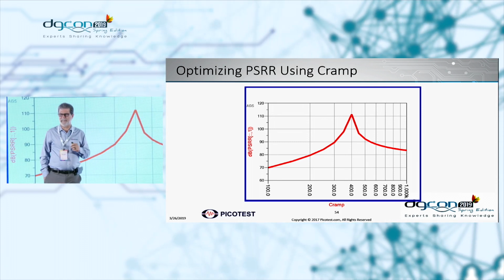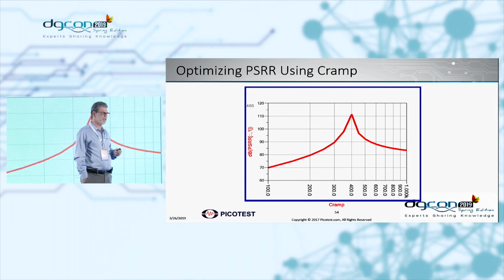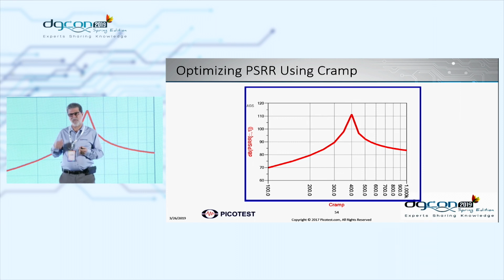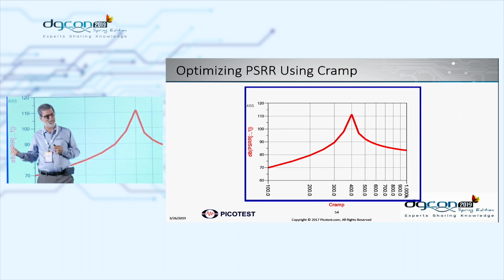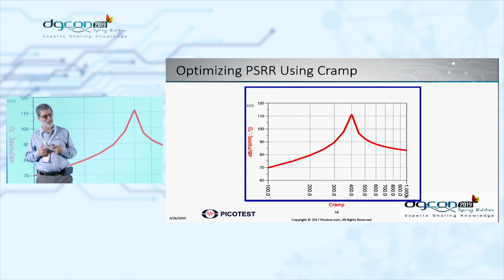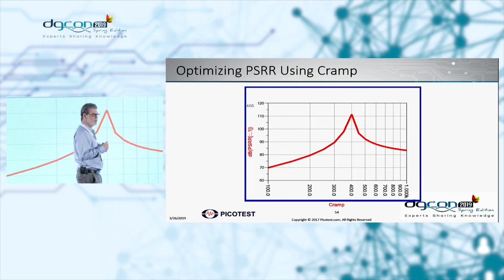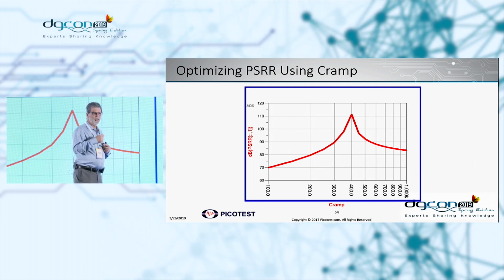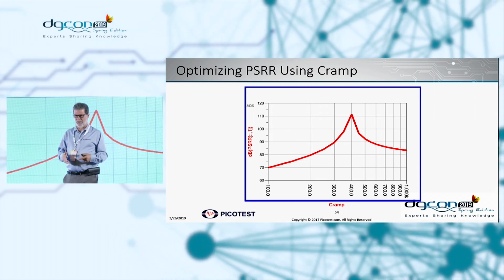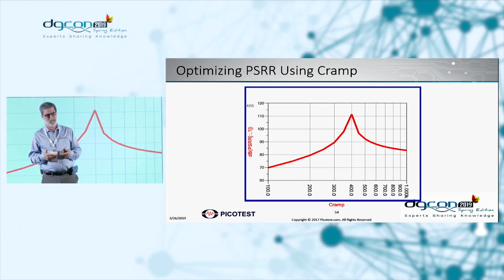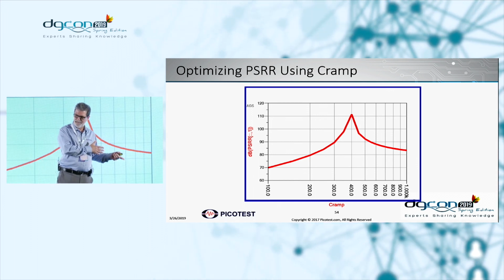I gave a workshop at Texas Instruments last year, and I asked them that very question. What they said is they crank up the slope compensator because they're afraid that customers will get into problems with subharmonic oscillations. And I said, I just want to repeat this back to you because I want to make sure I understood what you just said. You said that you were afraid some of your customers might run into problems with slope compensation, and so you guaranteed them a problem instead.